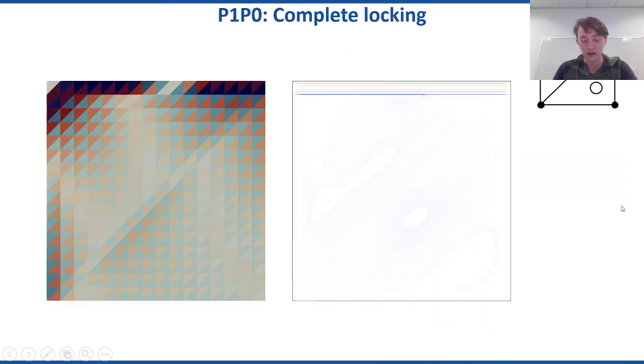And indeed what we see is that we get a completely zero velocity field. Now this is the velocity field, it's completely zero. Well, naturally, except for at the top nodes there, they have a fixed value. So clearly these are not very useful elements for these kinds of computations. They're completely locked, they give you a completely wrong solution field, and that's not what we're looking for.